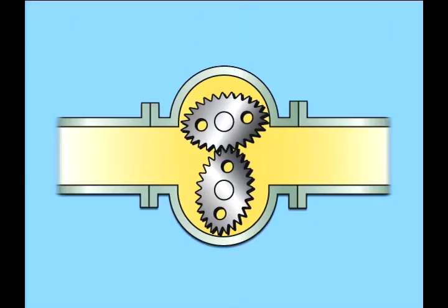Flow meters are attached to the fuel oil line for the main engine, engine generator and boiler. Ship operating costs can be reduced by decreasing fuel consumption. This also reduces emissions of carbon dioxide, the main factor in global warming, and NOx, the main factor in acid rain. Of the various types of flow meters available, here we will focus on the oval gear flow meter. This flow meter features a pair of oval-shaped gears that are rotated by the flow of fuel oil. Fuel flow quantity is determined by measuring the number of gear rotations.